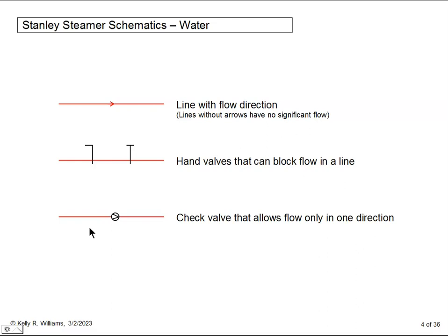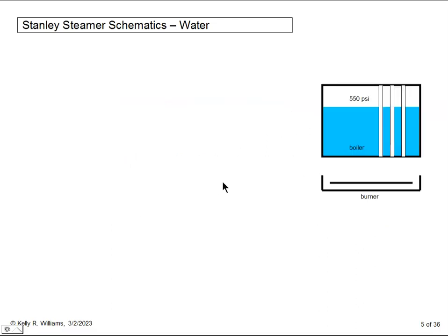So, let's start with the boiler. The Stanley boiler is a drum containing water with hundreds of narrow tubes like these connecting the top and the bottom. In the first of these presentations on steam and cylinder oil, the boiler is described in some detail, as well as the importance of keeping it 2/3 full of water. Check out that presentation for this information. It will be clear that, as we use steam to move the car, we're using water.